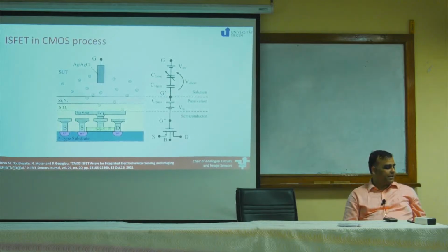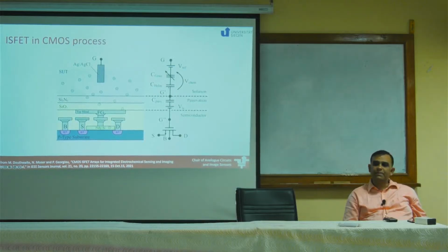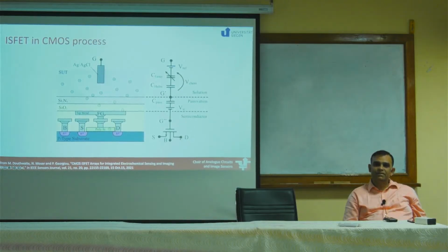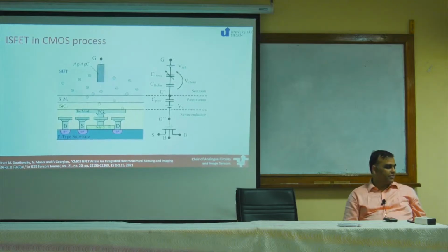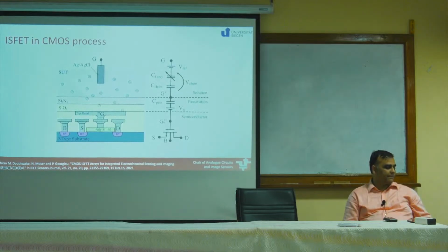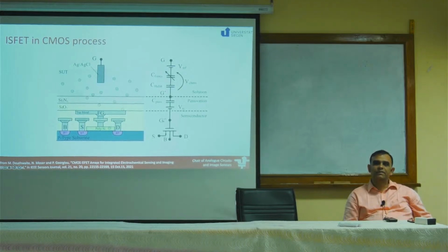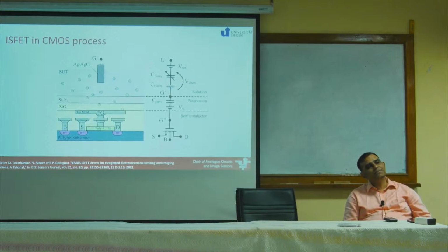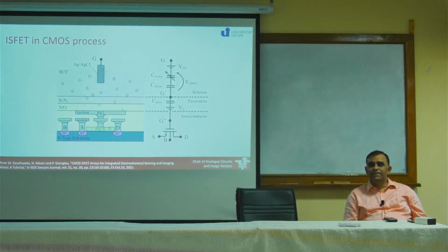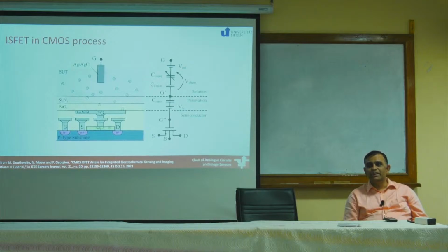So, I have got gate capacitance in series with passivation capacitance in series with the liquid capacitance. What voltage do I expect to see here? Can capacitors be used as potential dividers? Assume it is an AC voltage. If you look at it from an impedance point of view, if it is an AC signal, it can act as one.